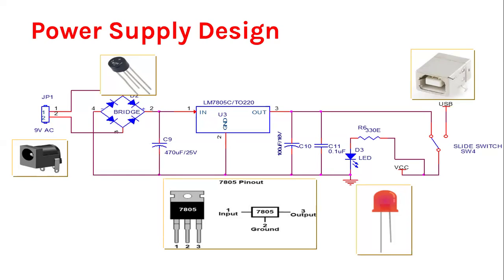Right. For any information exchange between the microcontroller and IO components, you must know the capabilities of the microcontroller. Suppose you directly connect it to the microcontroller pin, what happens? The pin is burned or breaks down, because its capability is 5 volts only.